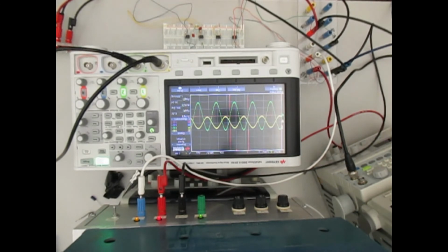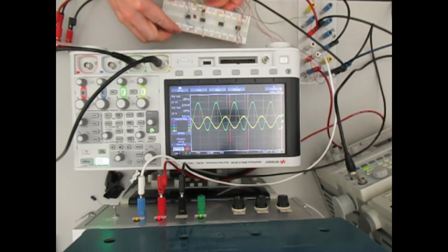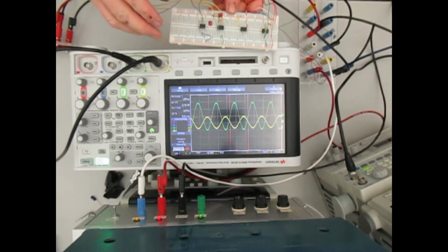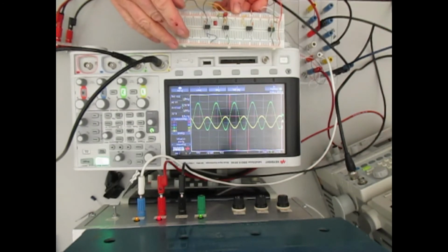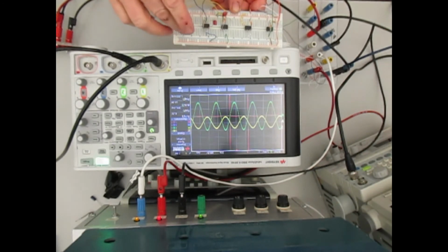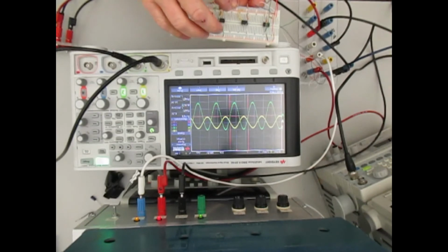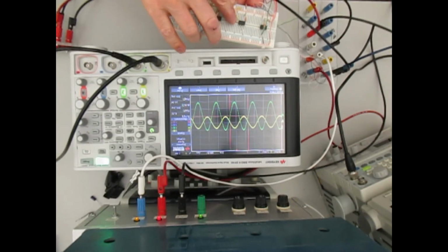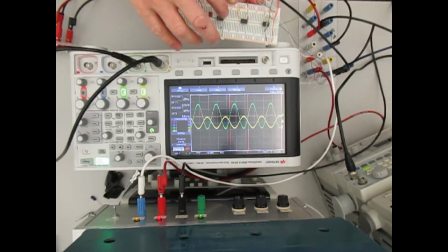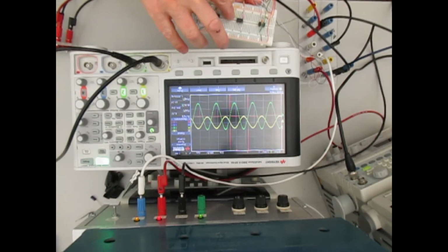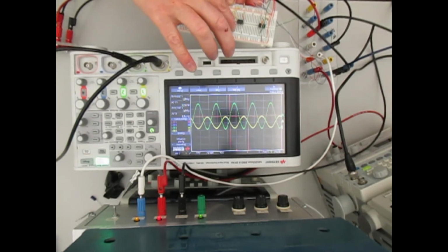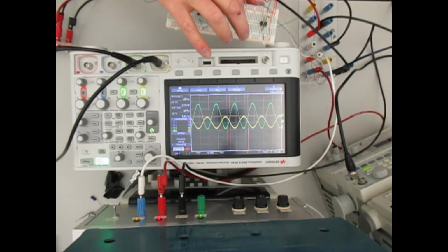Okay, here we go. This is a demonstration for lab number 5. Again, hopefully you can see, this is getting kind of cluttered here. But here, this is what we call a breadboard. And we can assemble our circuits on here. Basically the IC, here's our IC, right? Remember it has 8 legs, you can kind of see that. And it straddles the center, so there's no connection between this side and this side. But all of these lines are connected together here.